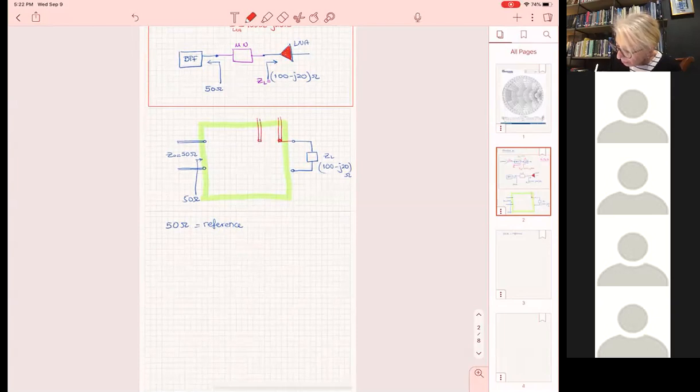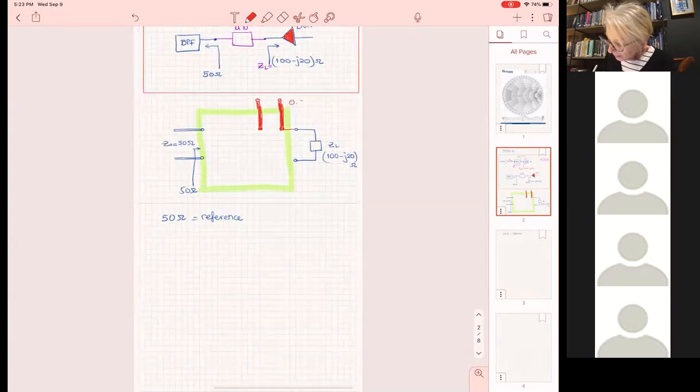And if I am microstrip, I will leave it open, because you remember what I said about microstrip? It's difficult to open holes in the substrate. It needs very special pieces. So I'll use an open stub. Now on paper, you can use a short too, but let me use an open this time. So this is an open circuited stub. And I put it in series because I have an impedance here. You remember that? And with impedances, I sum up when they are in series.